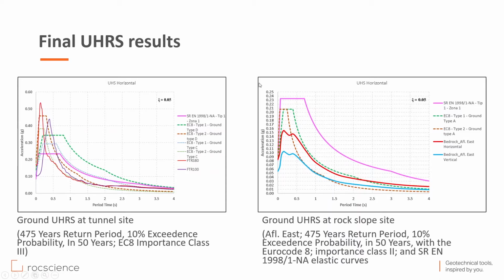But for the slope stability for the Csetățuia site, we calculated, of course, the bedrock response spectrum, and it was clear that because we have rocks, we could use the calculated bedrock spectrums without site amplifications.